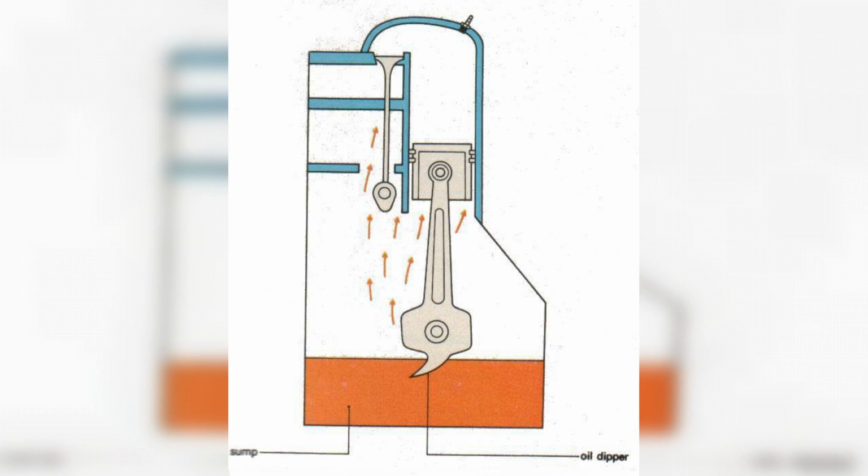Part of the oil enters the radiator for forced cooling. A bundle of relief and pressure-reducing valves ensure the normal functioning of the system, with significant fluctuations in the pressure pumped by the oil pump. Dry crankcase. This type of lubrication system is considered more efficient, but the technical realization of the dry sump method is more complicated, and the engine itself is more expensive.